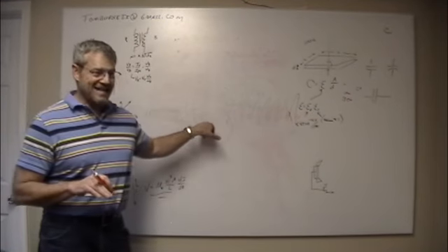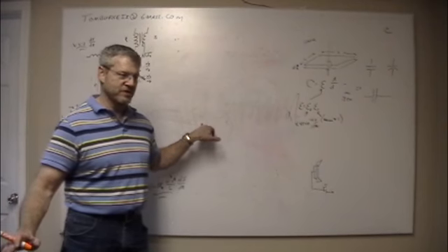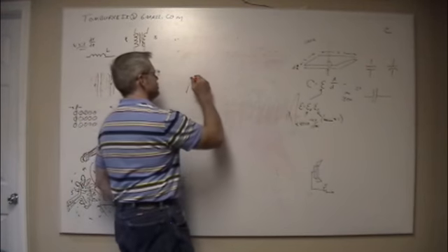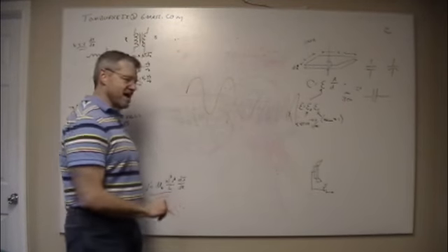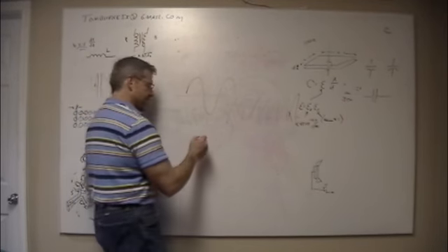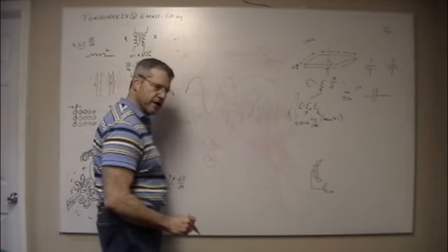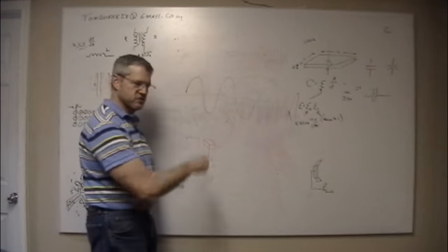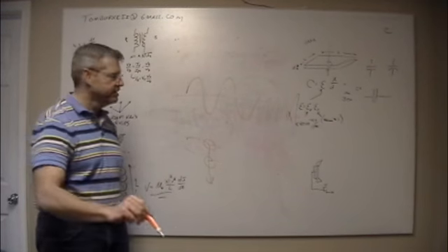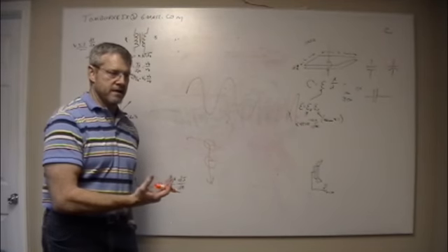I'm talking about Class A amplifiers. Every tube amplifier, for all intents and purposes, is a Class A. And we talked about that at one point where, gee, I can do a Class A and my signal looks like this, but damn, that uses a lot of power, because when I look at the transistors that are driving this thing, they're always on. There's always current going this way to ground and being wasted and using lots of power to get very little output. And holy cow, that costs a lot, right?